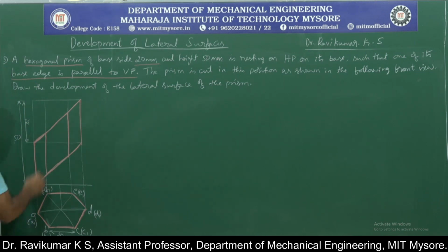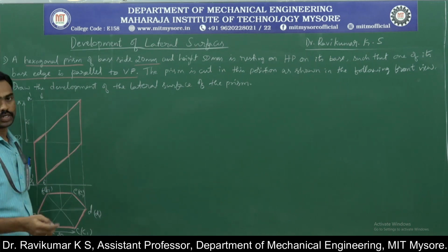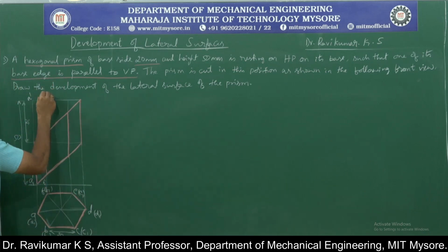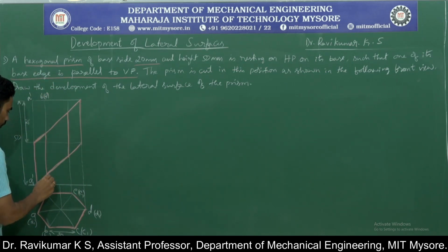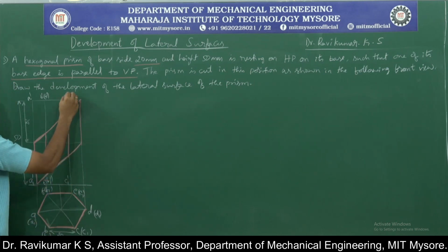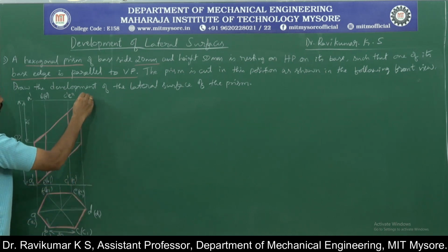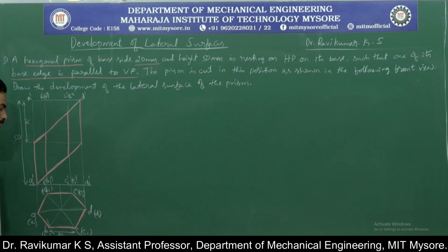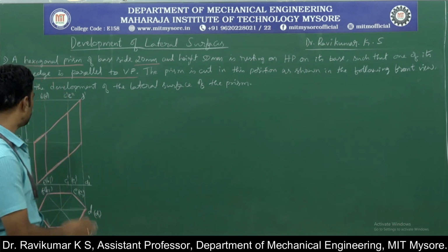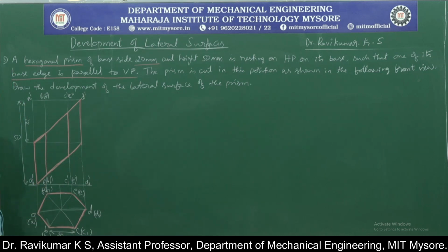So similarly the front view, this is A dash, this is A1 dash, this is B dash, B1 dash, also B dash and F dash. B and F, there are 2 points which are overlapping. Therefore you will find F dash also here and F1 dash also, which is in bracket, which is not visible. Similarly C dash, C1 dash and E dash, which is in bracket, E1 dash, D dash, D1 dash. Okay. So this is the front and the top view of the said problem.